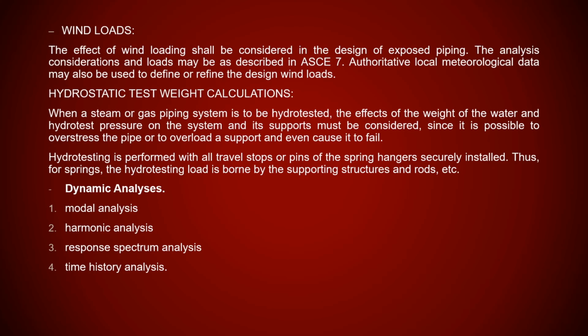If we are doing a dynamic analysis, you have four calculations which you are using in the dynamic analysis: modal analysis, harmonic analysis, response spectrum analysis, time history analysis. Modal analysis is mainly used for predicting the natural frequency of the system. So modal analysis, you can consider it something in between the static analysis and the start of the dynamic analysis.